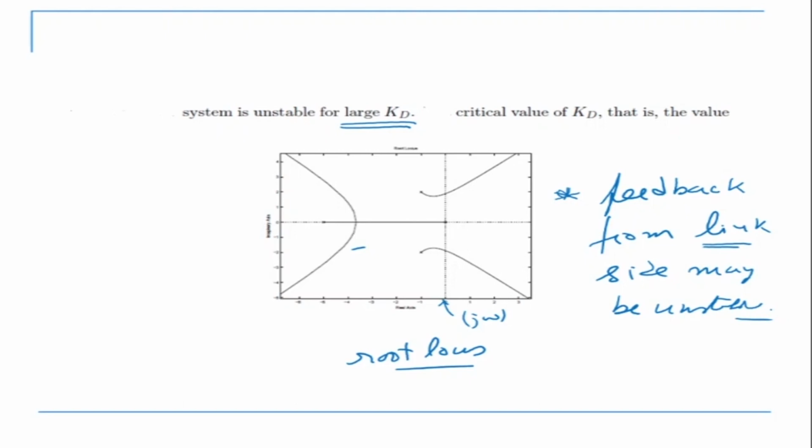Okay, so today first we looked at control of a single joint. Then we looked at series elastic actuators, where we are trying to introduce stiffness in a joint, and then we are trying to control the motor such that I get a desired position on the other side. And as I was saying, when we come to biped locomotion, we'll see that these kind of actuators are used these days, essentially because we need to absorb the kind of impact that is coming.